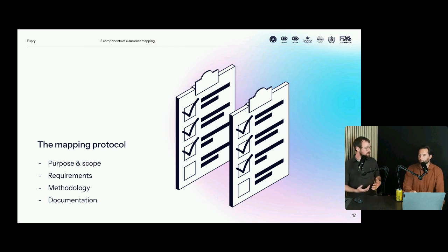As a rule of thumb, we would normally like to say do 2 weeks. If you're not under time pressure, it doesn't matter that much to do 2 weeks, because you'll set up the loggers, they'll gather data, you'll go do something else, monitor it remotely, and then come back. So yes, it does influence it. Smaller units like fridges and freezers will show those variations much quicker, and we would normally recommend doing that in days instead of weeks. Also, just the sheer size and the amount of work you have to put in compared to a smaller fridge is a different level. Absolutely, it's much more complex.